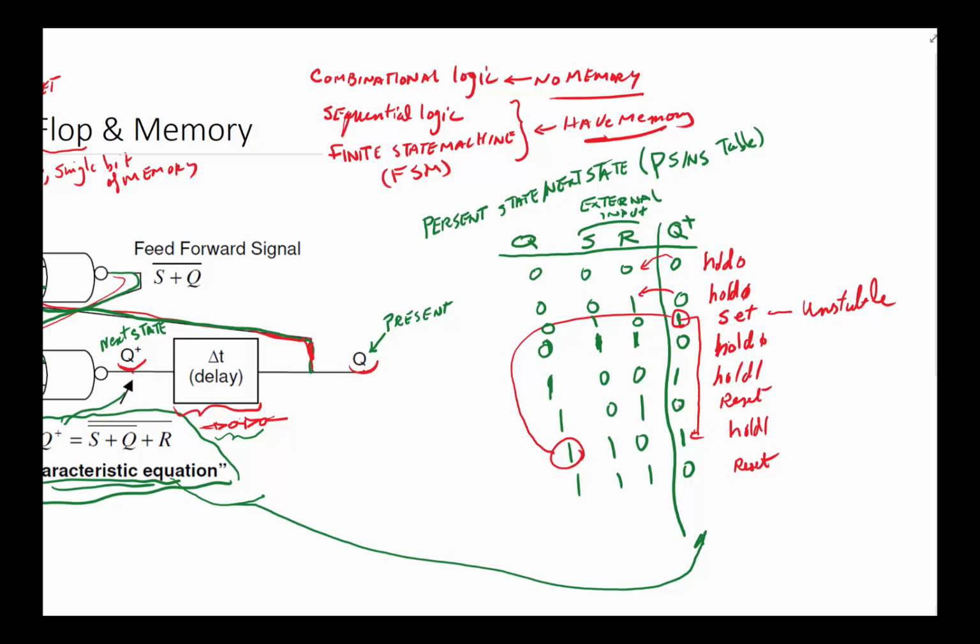This is another place that something interesting might happen because if you look, let me use a different color, it's getting kind of messy. So if I come to this reset state, my Q plus is now here, which means over a short period, Q is going to change. If Q changes, I'm going to end up at 0, 0, 1, 1. So this state actually goes up here. And then that state is stable. So this is another unstable state. And finally, the last one is this one, which is unstable because this 1, Q1, is going to shortly change because Q plus is 0. So eventually I'm going to move all the way up here, so we have a few unstable states, okay?